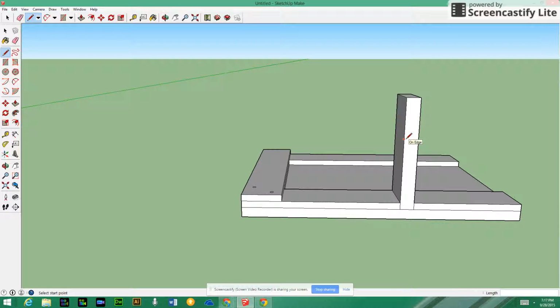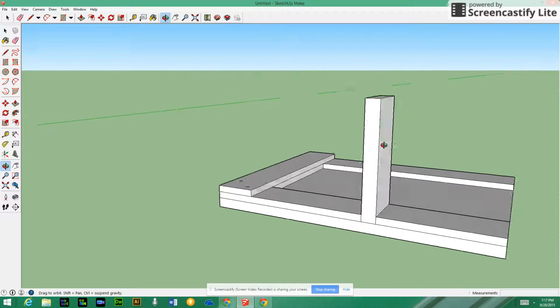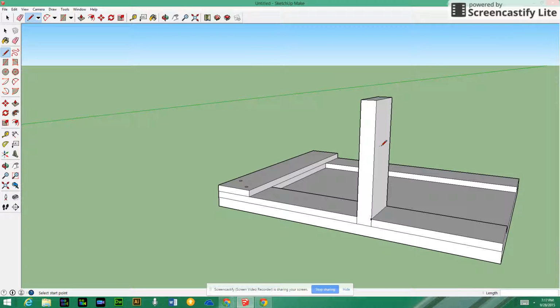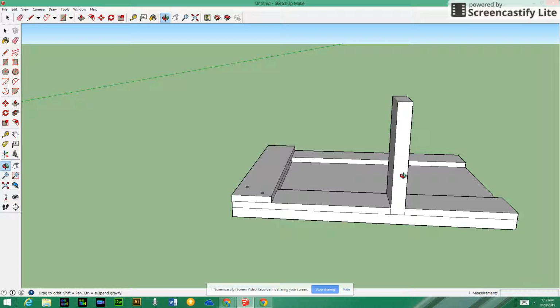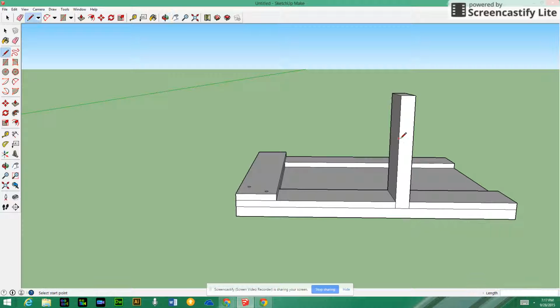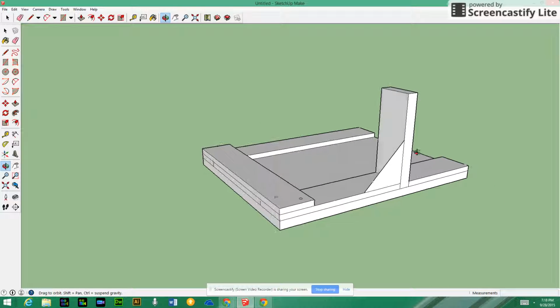So you're going to want to put a triangular support in somewhere. You guys probably remember from science that triangles give you a very strong rigid joint. You don't want a mobile joint here. So we're going to put in some kind of a fastener for stability. There's several ways of doing this in SketchUp, and there's several ways of doing it with wood. A very simple way would be to take, and I'm going to make that a 45-degree angle. So as soon as it goes pink, we have a 45-degree angle. And I'm just going to push that across.